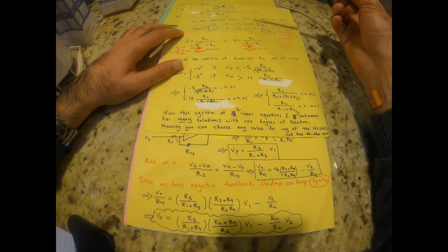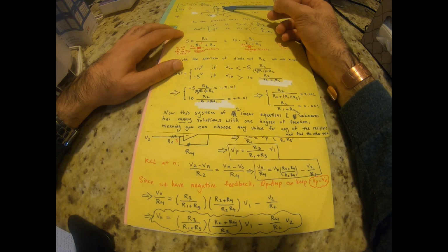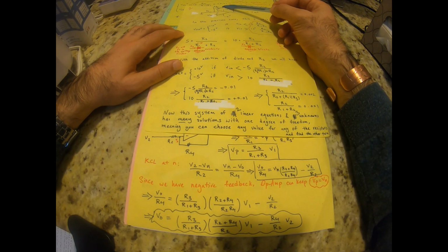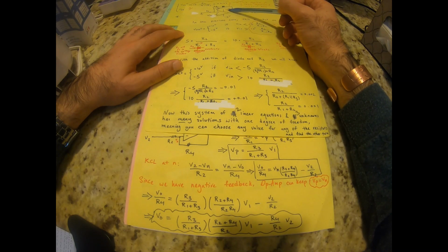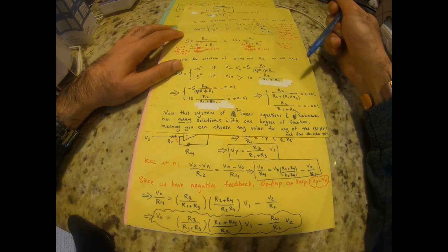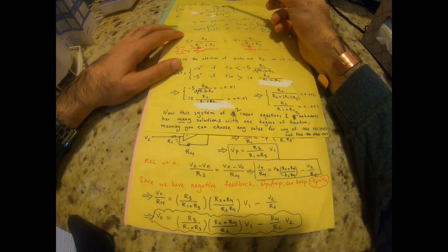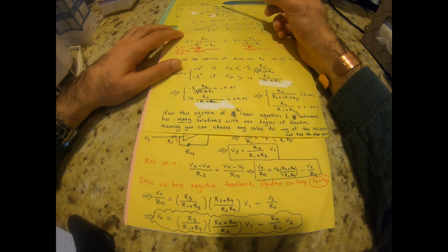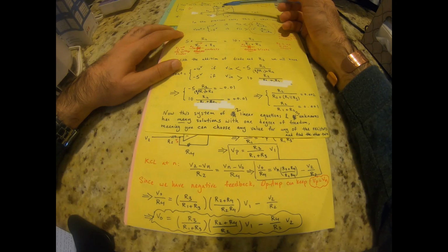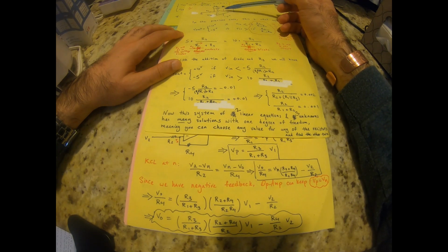by adding a parallel resistor with a diode in the right direction. So you just have to make sure you add this diode in the right direction. That depends on the values of the positive power supply and the negative power supply. For example, if this diode for this case was pointing the other way, it would have actually made the problem even worse.